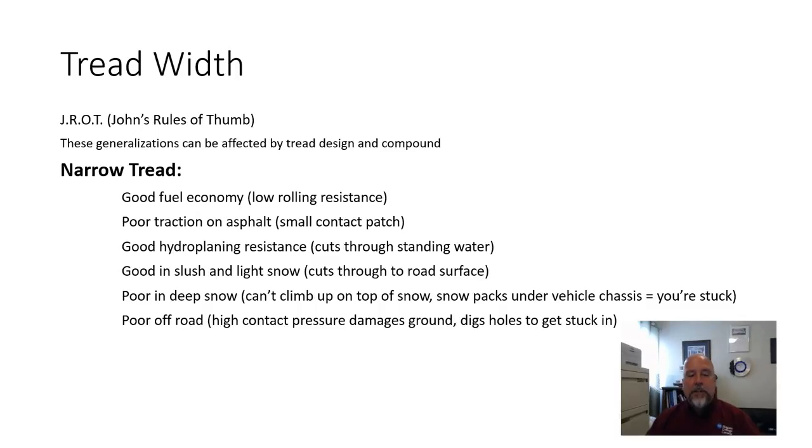They tend to be good in slush and light snow for some of the same reasons. They cut through that overburden of snow or slush down to the road beneath and give you reasonable traction. In deep snow, it can be a problem though, because you may need a wider tire in order to get a flotation effect to get you up over the snow. In very deep snow, these can just cut through, and if they can't actually reach the ground before the undercarriage of the car is sitting on the snow, then you're stuck.